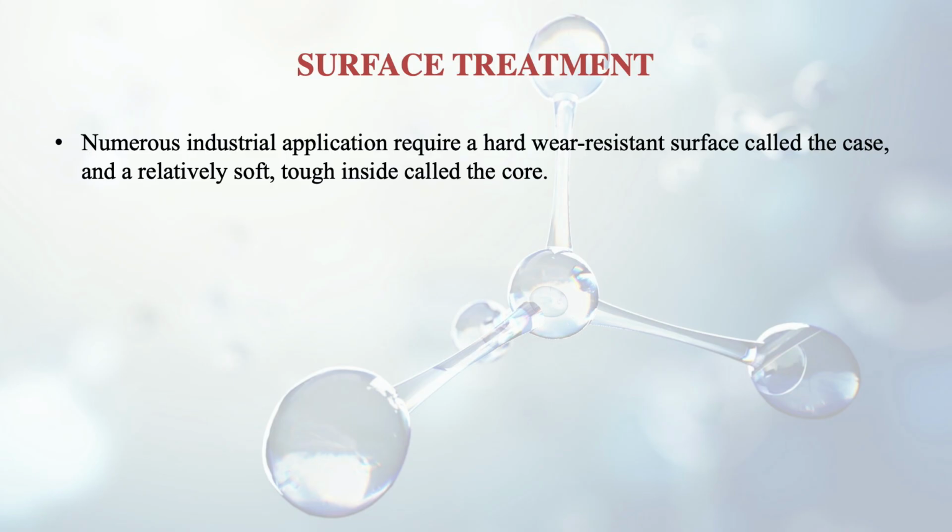So what is surface treatment actually, and why is it needed? There are numerous industrial applications which require a hard, wear resistant surface, which is generally called the case, and inside we need a relatively soft, tougher material. That soft inside is known as the core. For that purpose we do the surface treatment.